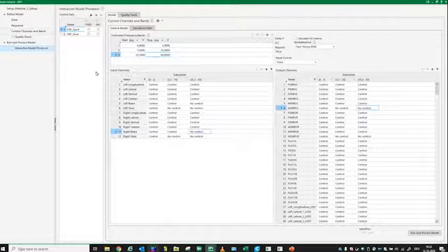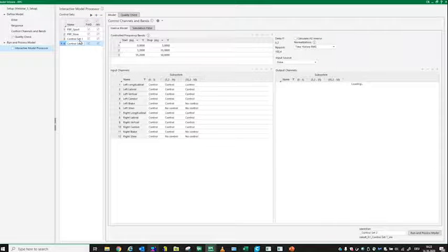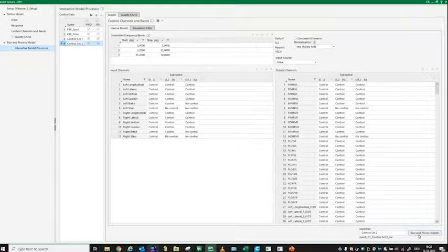And now you can imagine if you have several ideas how your system can converge and how you want to start your iteration process and be successful, you can add a bunch of FRFs here with different control sets. Hitting the run and process model button will create the FRFs each time with the appropriate settings. So if you have a simulation filter set, if you have set the H2, for example, which you see here, everything will be created and given a name.